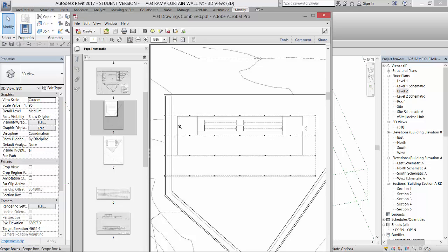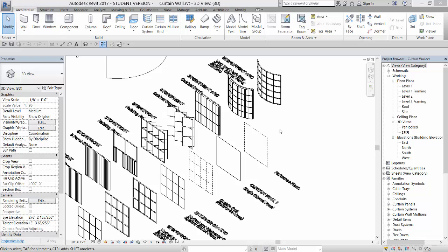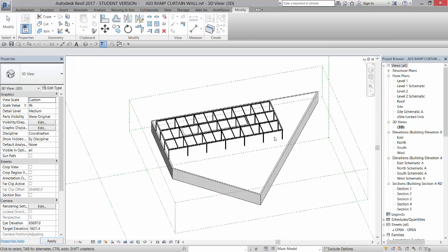And so what we're going to do is put in the curtain wall 1, and we're actually going to create our own curtain wall from that. We're going to do that by duplicating the curtain wall system and then duplicating the actual exterior glazing panel that's creating that. So if I minimize this, basically we're going to create a new system, which is the overall system for the curtain wall, and then we're going to create a new panel that's applied to that system, and this panel has a relationship to that system that we will update. So let me close this and we'll come back.